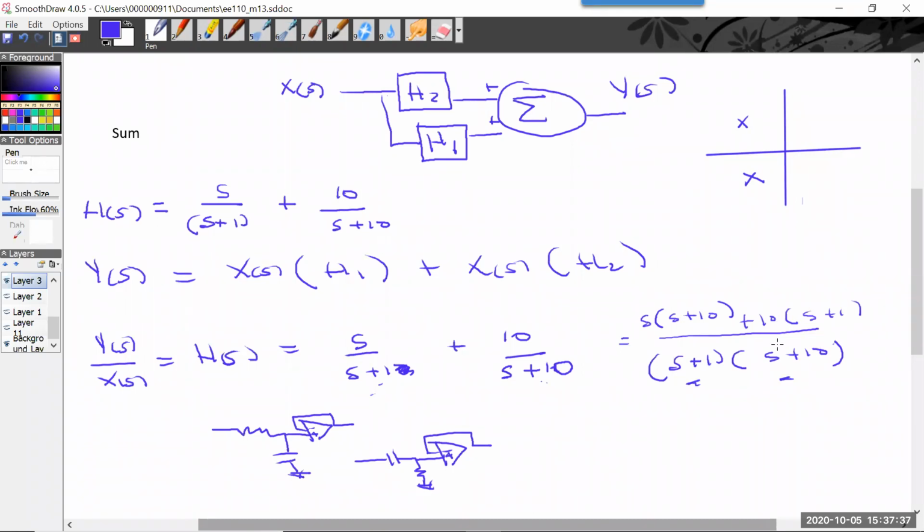So just multiplying real poles or real zeros times each other does not make complex poles. And so when you really have the same energy storage element, capacitors or inductors, you can't get complex poles.